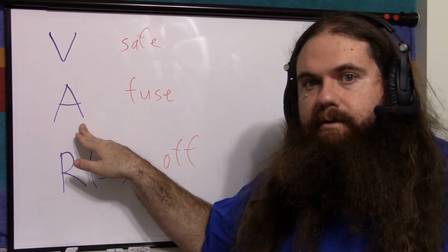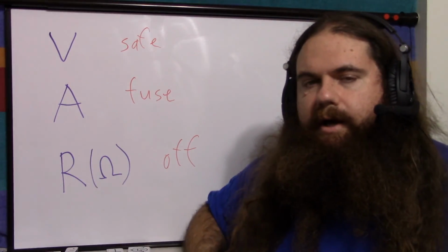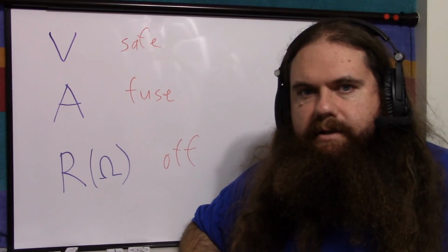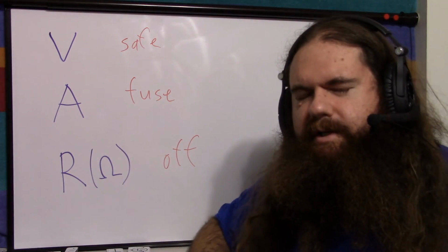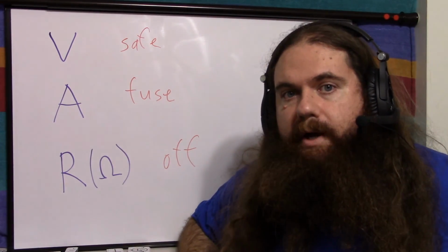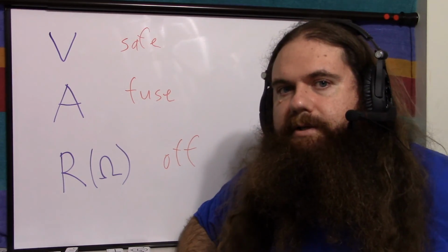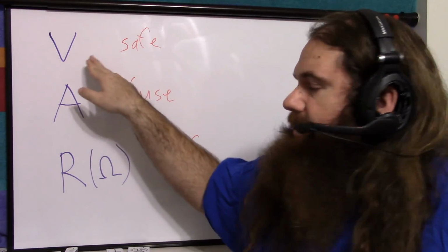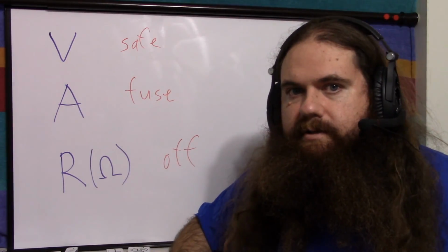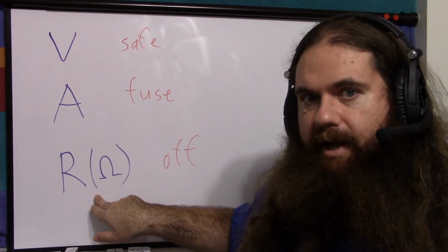But just like here, what if that port is generating a voltage? And it is, it's a signal. So right now, I don't know what impedance the port of a computer expects. If I plug the amp meter in to see how much current is going through, I might fry the circuit, because it might be expecting anything; anything you plug in there will limit the current. So that's why I've labeled voltmeter safe, because it's passive and it has a resistance. Amp meter is passive but very little resistance, and this one is active.